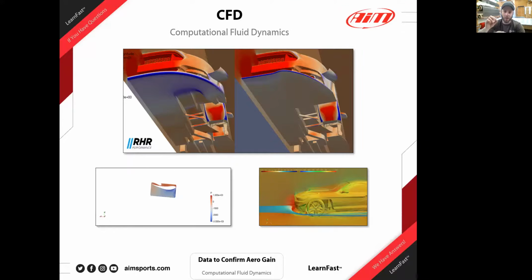And the pictures we're looking at are just a few screen grabs of hundreds and hundreds of runs that he's done for us. Like, all right, we ended up changing this little bit, here's the numbers. But the two we're looking at now, tunnels in the splitter, are a huge front downforce generator with very, very little drag increase. Those were used to develop the splitter tunnels that we have. You can see the darker the blue, the lower the pressure.